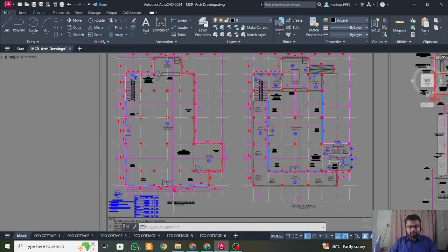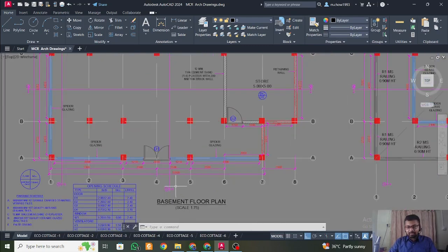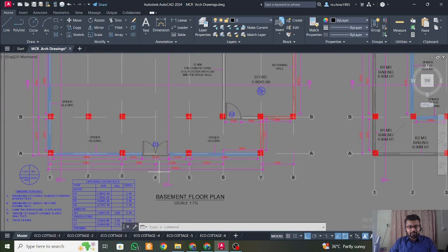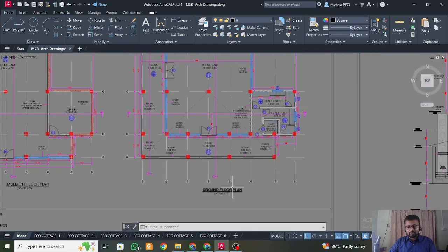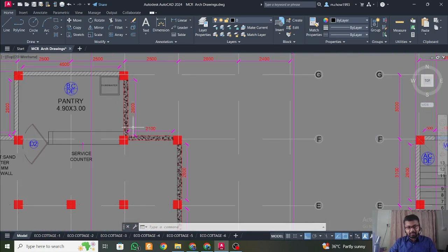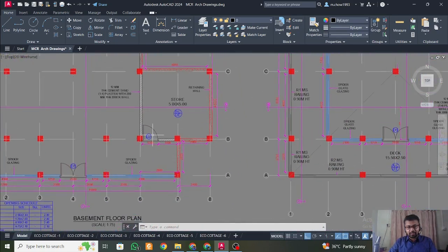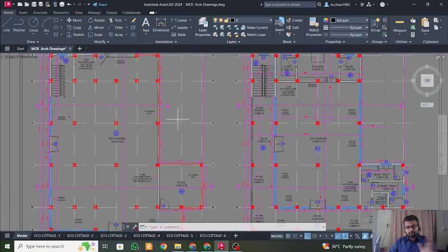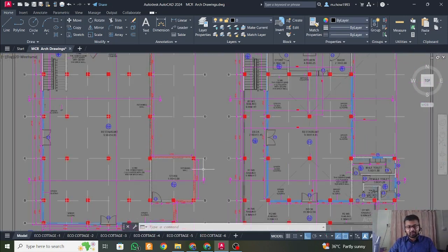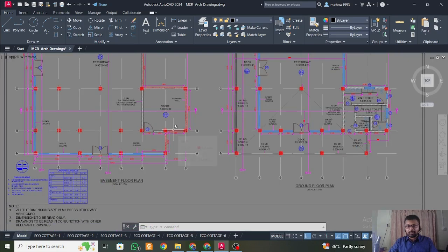So we have today a plan, a PDF which you can download here. I provided it, and basically we need to make this basement plus ground floor. About the basement, you can have an Excel sheet to make the retaining wall. Here you can see the retaining wall in one direction. There is actually a road going on, and there will be some filling, so that's why they're providing a retaining wall in this direction. So retaining wall design you can do manually here.